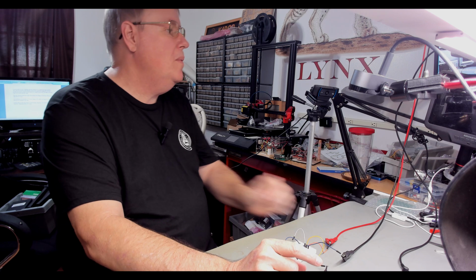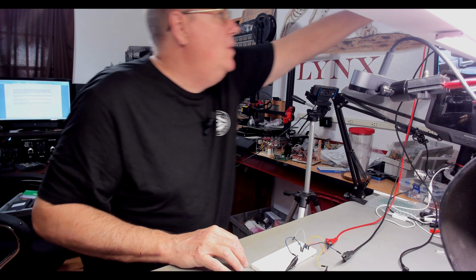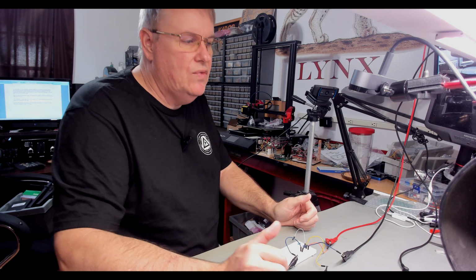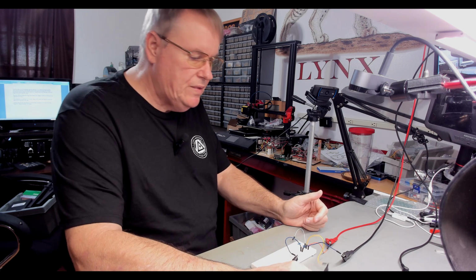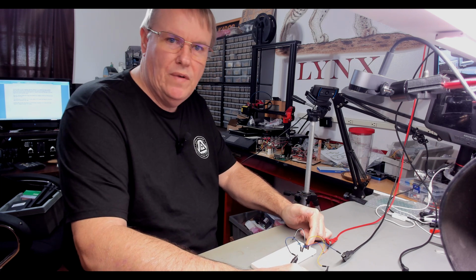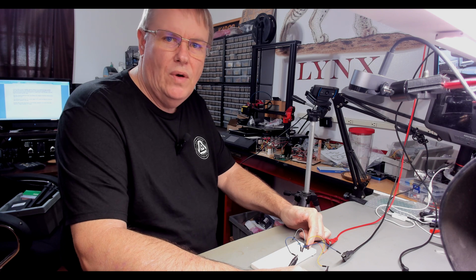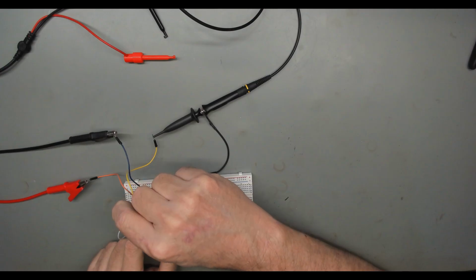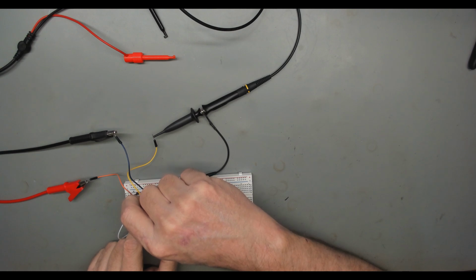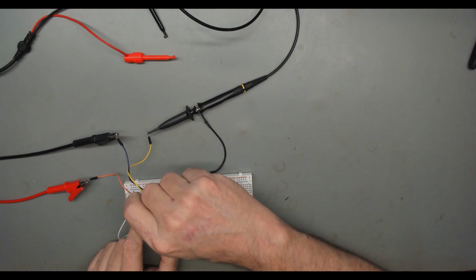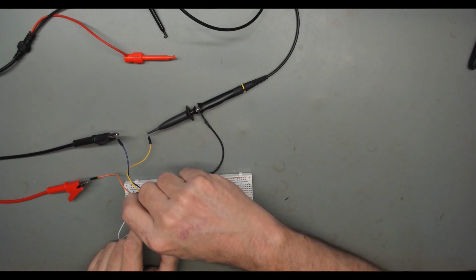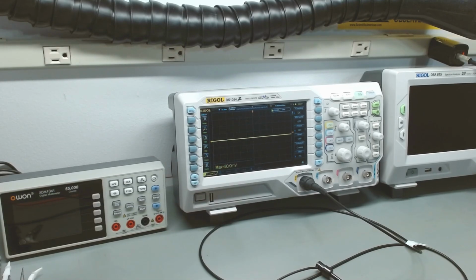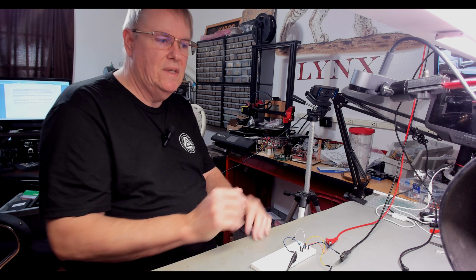So if I turn my power supply on, we should see some voltage. And lo and behold, we do. We're getting 6 volts. So currently, the oscilloscope sees 6 volts at the input of the capacitor. Now, here's the question. Will we see 6 volts at the output of the capacitor? So let's move our, this is just the probe of the scope, over to the output of the capacitor. And notice we do not. We do not get our 6 volts through the capacitor. Our DC is being blocked.